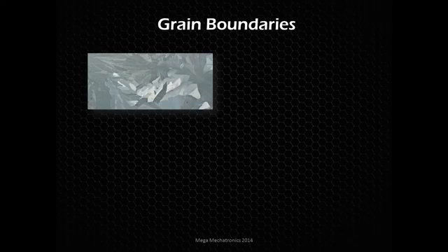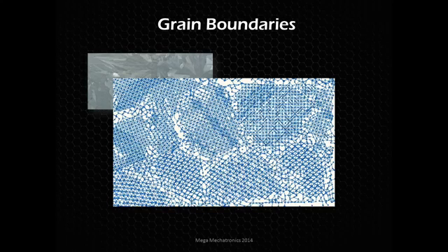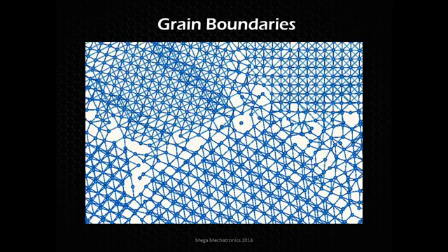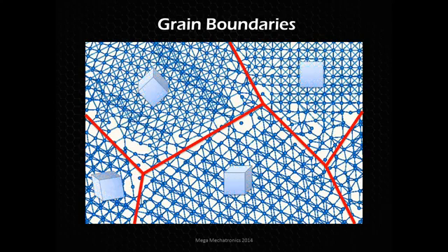And when these crystals start forming randomly within the material, they're going to be crystallizing in different orientations to each other. This is an example of a galvanized surface, where the zinc is crystallizing in different orientations, and we see the light refracting off of that in different ways, so we can easily make out the grain boundaries. Looking at a computer-generated model, you can see the crystal structure, a uniform grain, and the grain boundaries around it. We zoom in even closer, outline those, and get an idea of the different orientations.